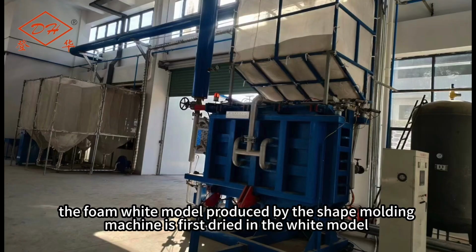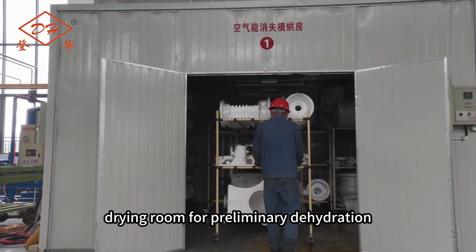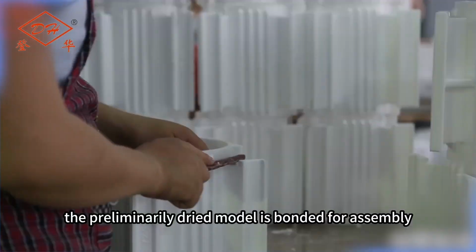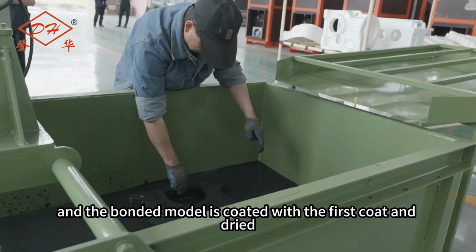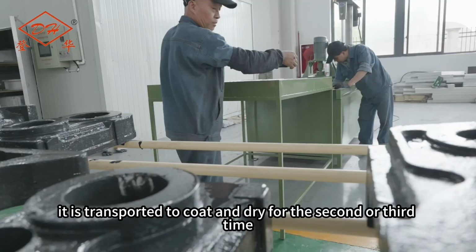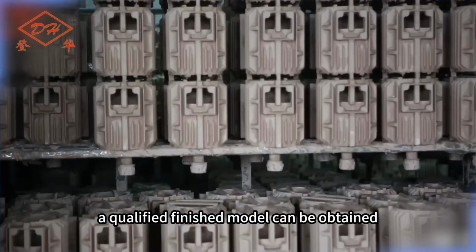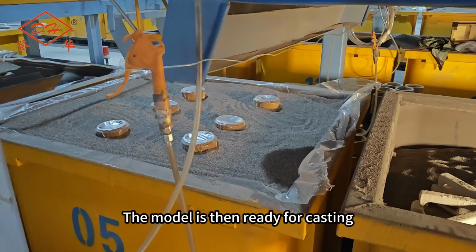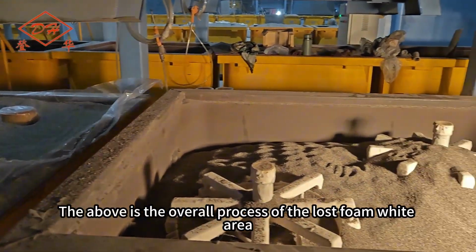Secondly, the foam white model produced by the shape molding machine is first dried in the white model drying room for preliminary dehydration. Then, the preliminarily dried model is bonded for assembly, and the bonded model is coated with the first coat and dried. After that, it is transported to coat and dry for the second or third time. After drying, a qualified finished model can be obtained. The model is then ready for casting. The above is the overall process of the lost foam white area.